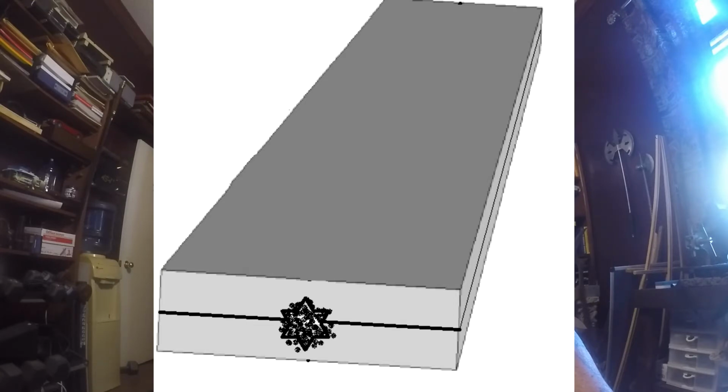If you don't overheat your metal and you pour it at a good pouring temperature, the skin that represents the mold cavity will solidify first, and the molten metal inside that skin will feed the thickening of that skin until it solidifies all the way down to the very center of that mass.